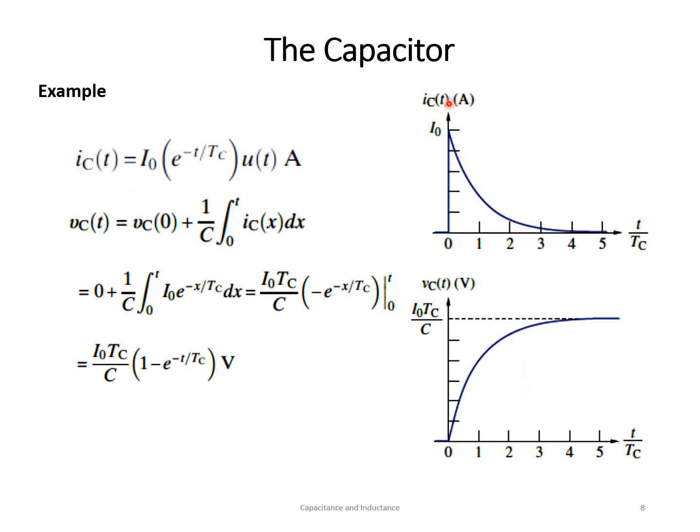Again, for the capacitor, if this is the waveform of the current flowing through the capacitor, we have discussed this composite waveform in chapter number 5, and the mathematical expression of this composite waveform is shown over here. It is I naught and an exponential function multiplied by u(t). This u(t) is to emphasize that the current is 0 from t equal to minus infinity to 0, and the current starts from t equal to 0.